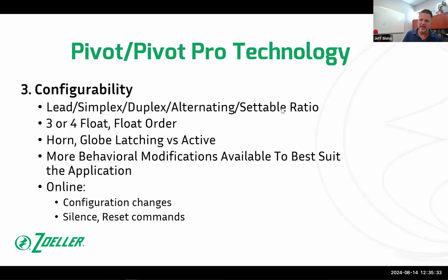And it'll kind of go through that process until somebody calls attention to it. But there'll be an alarm, etc. But the point is you're not running simultaneous pumps. And then the lead, what that means is we used to sell what was called a lead lag selector switch.